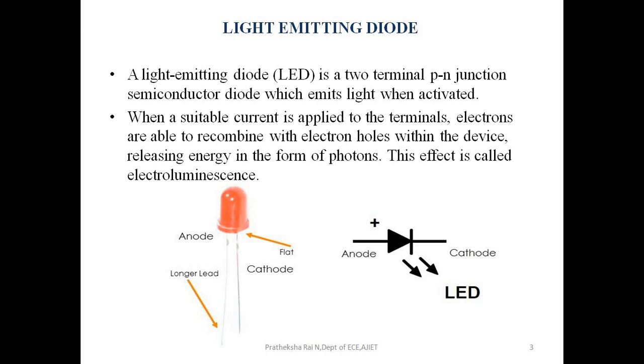So, light emitting diode is most commonly called as LED. It is almost like a PN junction, but we can tell that it is a specialized type of diode. Specialized in the sense it is made out of a specific semiconductor and it is having a specific amount of doping. That is, it is basically just a specialized type of diode as they have similar electrical characteristic of PN junction diode. This means that an LED will pass current in its forward direction but block the flow of current in the reverse direction.